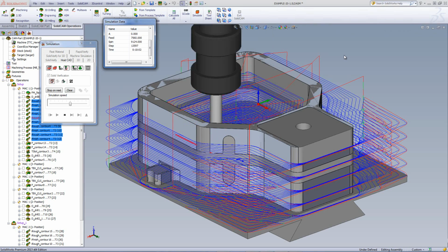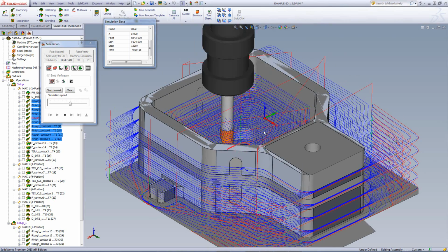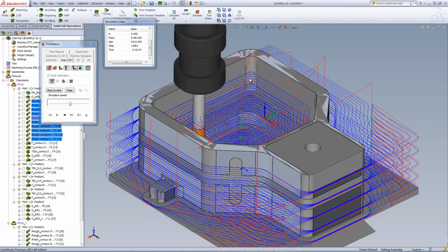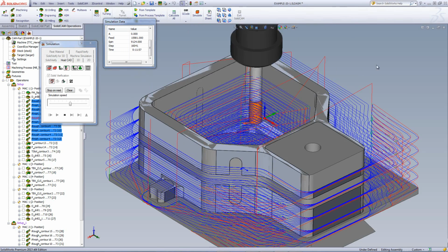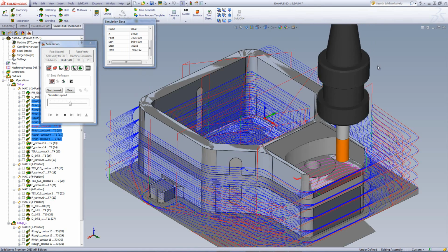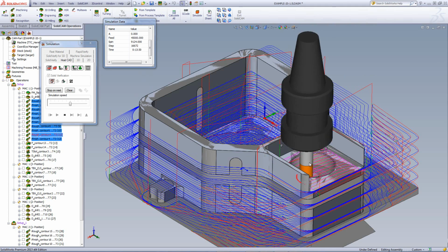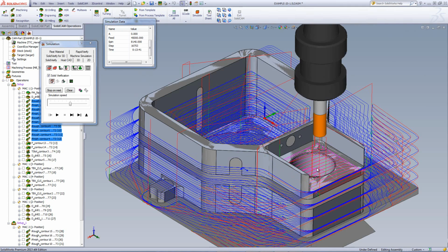First, in this particular case, using the morph spiral to mill out the pockets, and then finishing off the corners using the trochoidal cuts until it gets to the very bottom of the part, and then doing the finish cut. Then of course it does this pocket over here, and then this area over here. Now, the entire time for this entire part, from beginning to end of milling the surfaces rough and finish, took just over 13.5 minutes for this large block of aluminum.